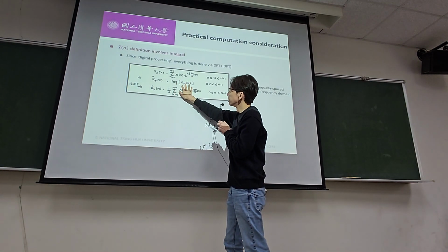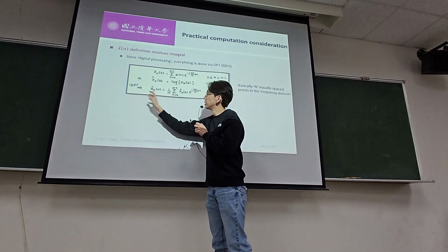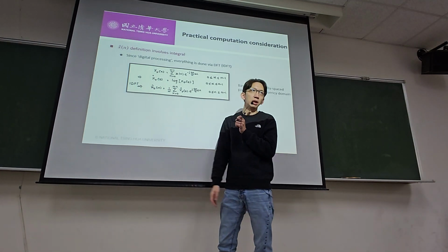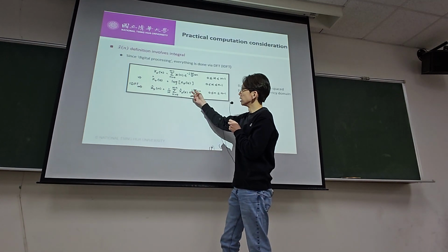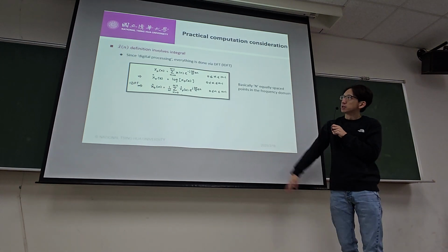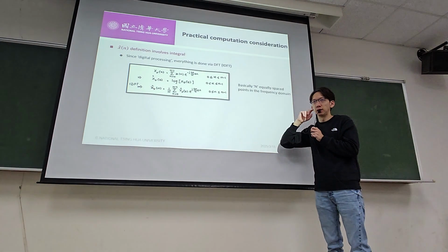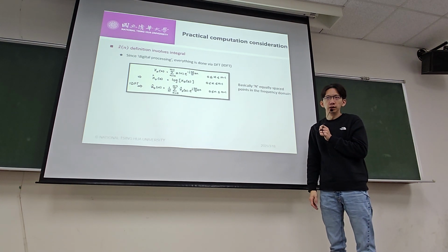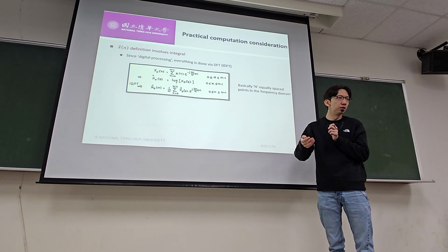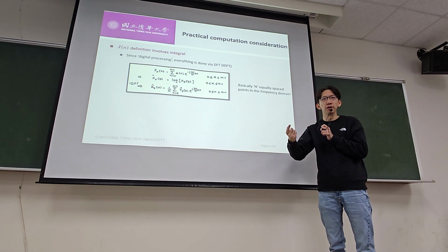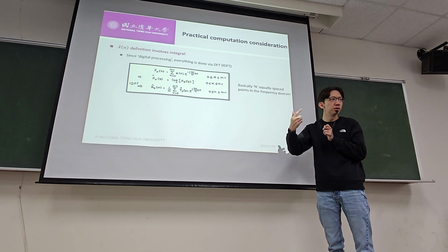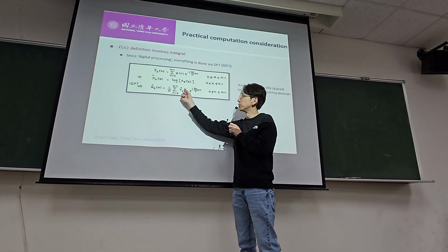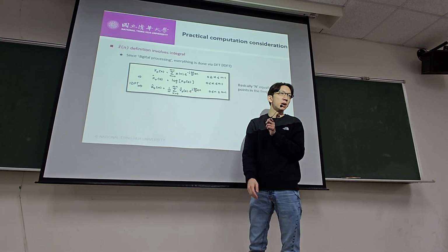Then you take a log on this. Instead of doing the inverse transform using integration, we do an approximation called the IDFT, the inverse discrete Fourier transform, and split the 2 pi into N. So again, nothing special about this process. In your standard Fourier transform, you don't actually do integration. In your computer you do a fast, discrete Fourier transform where you equally space the 2 pi into N points, and when you do the inverse Fourier transform, you again split that 2 pi into N points back to the original domain.